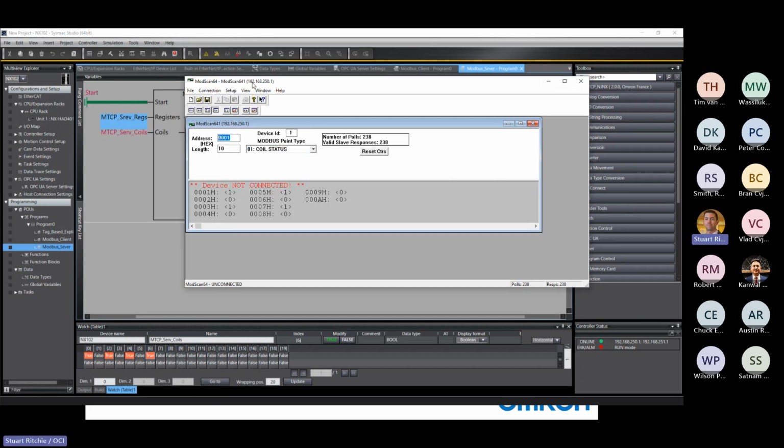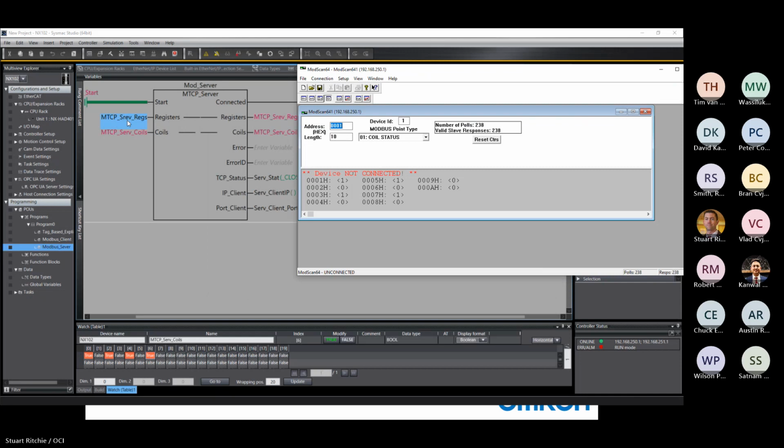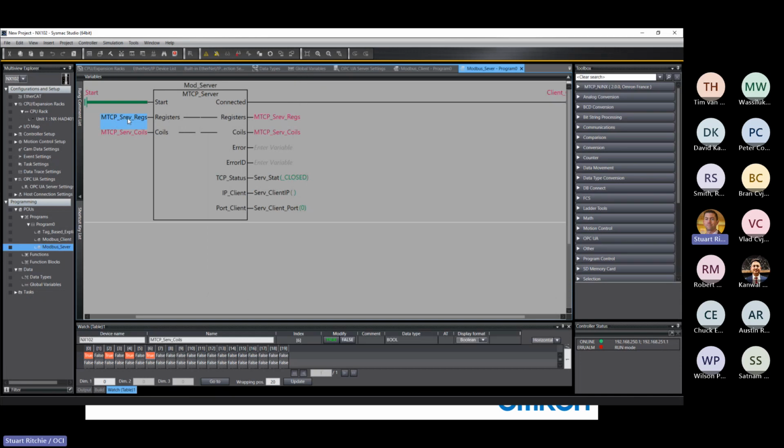Modbus generally starts at 1. And in our array, when we are asked for register 1, say, let's say it's 30,001 or 40,001, we treat them the same in the PLC. We are going to respond to a request for register 1 with array index 1.